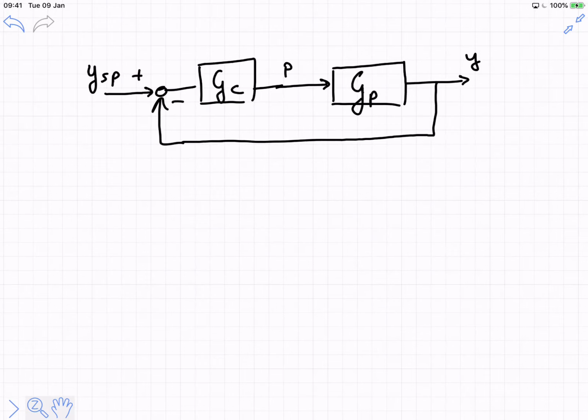Everything that we are talking about when we talk about a PID controller happens inside of that GC. So in a very real way, when we design a controller, we are obtaining an expression for GC. Later, we'll be doing this in the Laplace domain. You'll see that chapter 7 takes a time domain approach, because obviously, real things do not exist in the Laplace domain by themselves. If you build something, they just exist in the time domain, right?